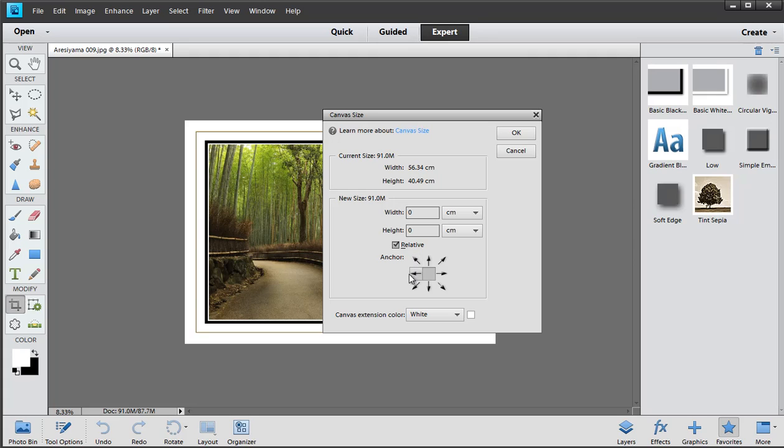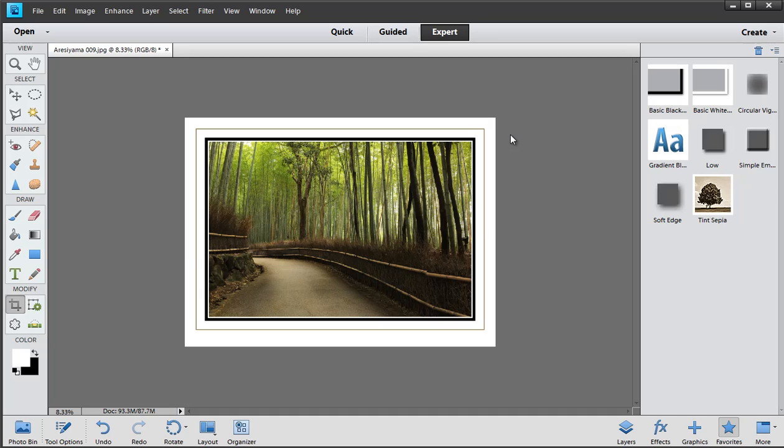This little fella here is a direction finder. It actually points the direction of where the real estate, the added border, goes. So if I click up at the top and I say, look, just increase the height by, let's say, another centimeter, it's just going to shove it downwards. So what you'll see here is no expansion of the width, only the height. There we go. Very simple, and that's how we make borders.